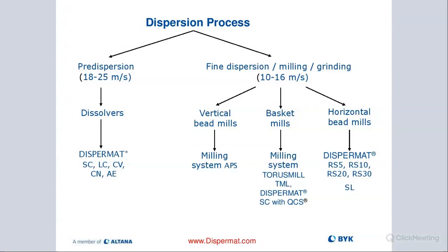If we nano mill, we're putting in even more energy. We have a lot more beads. There's a lot of energy that we're putting into a mill base. So we see that it's very easy to get the temperature up very rapidly. So it's really important to have a very, very good quality, high-powered cooling system that at least matches the power output of the disperser or the mill.